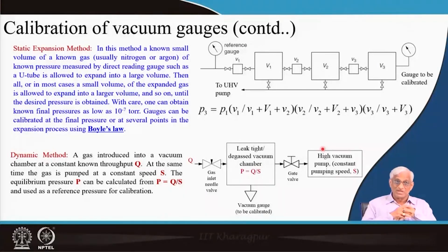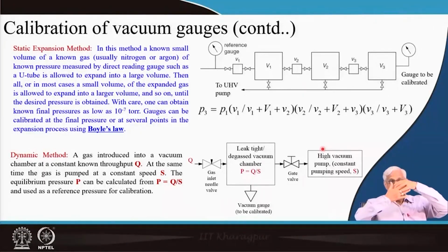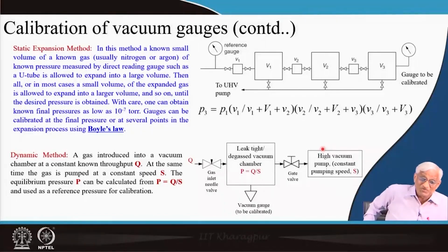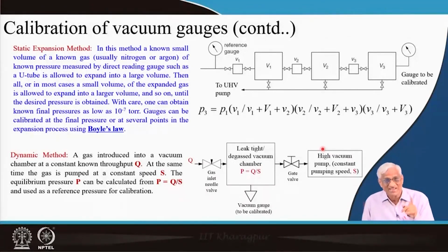Depending on the impurities coming, the Penning gauge needs to be cleaned with ethyl alcohol or something, so that a fresh surface will be there, otherwise the ionization concept will be different. That I am not going to cover right now here. When we go for applications, whether it is the chemical industry or the semiconductor industry, we need to take, it is called gauge care, gauge cleaning, that we will see later.